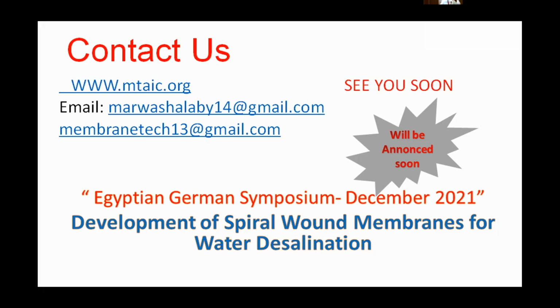So if I need to target more than one pollutant, organic and inorganic ones, together with the oil emulsions, I need to have stages. The first stage gets rid of the oil, and then I go to another type of membrane used selectively for another pollutant. Because when you are selective, you can have good operation, good performance, and avoid maintenance problems. Because as you put difficult conditions or difficult pollutants in the feed, you will bear a lot of problems during maintenance and operation.